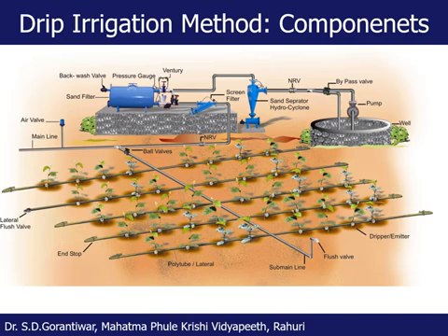For monitoring the pressure, we have to measure the pressure. For measuring the pressure, especially across the filter, there is a necessity of the pressure gauge. If there are pressure gauges across the filter, and the pressure drop across the filter is beyond the desired limit, it shows us that this is the time the filter should be maintained and cleaned. It also shows us what the pressure is at the different points, and if the pressure is less than the desired one, then we have to take corrective measures so that we get the desired pressure.